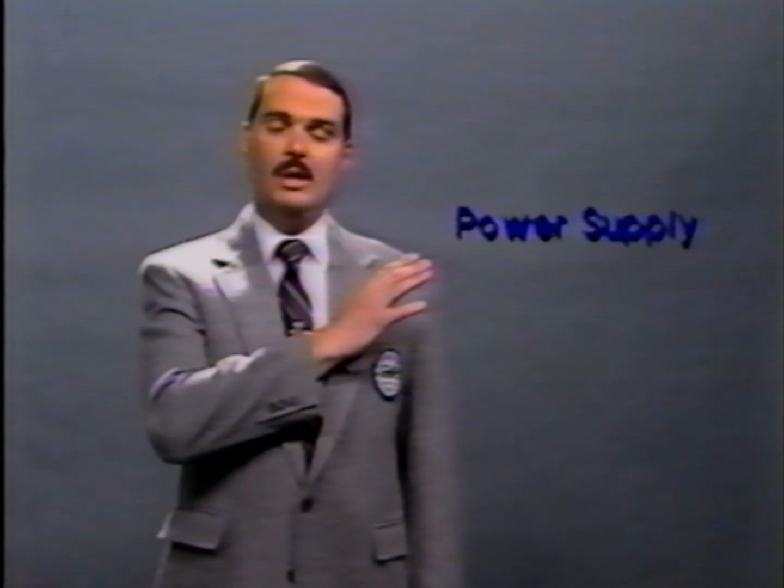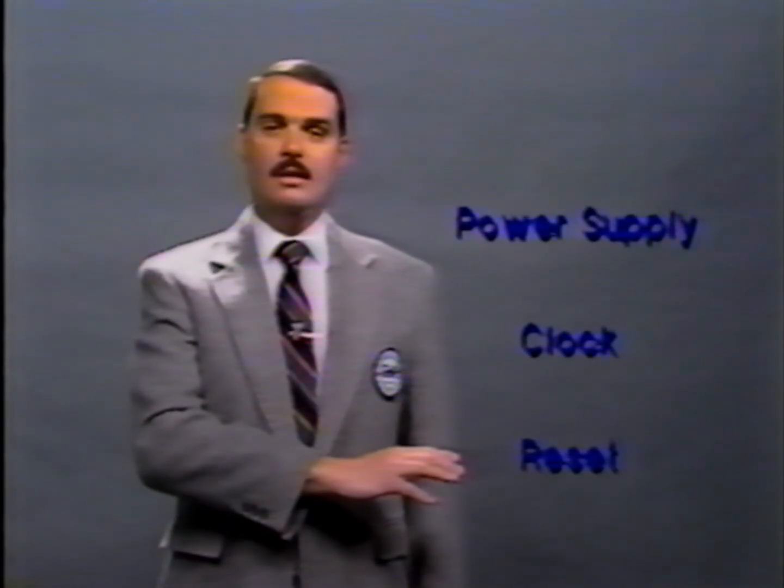Remember that just because a reset pulse is applied to a microprocessor, it does not always follow that the reset operation actually occurs within the microprocessor. The microprocessor may be defective and unresponsive to the correct reset signal. If all other tests yield valid results, suspect the microprocessor. These three signals, then, are essential for every microprocessor: the power supply, the clock, and the reset. If any of these is missing or inadequate, the microprocessor will fail to operate normally.